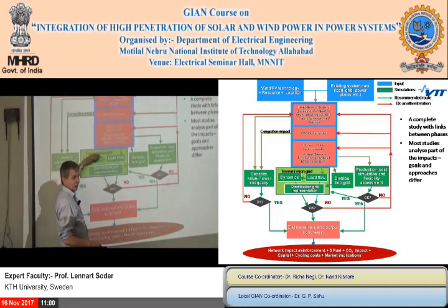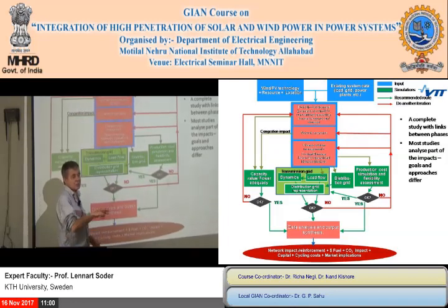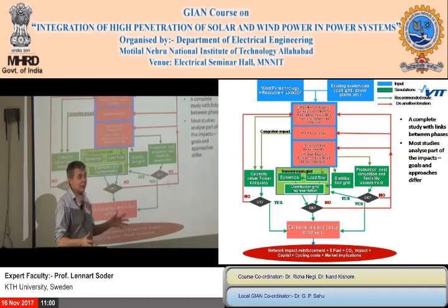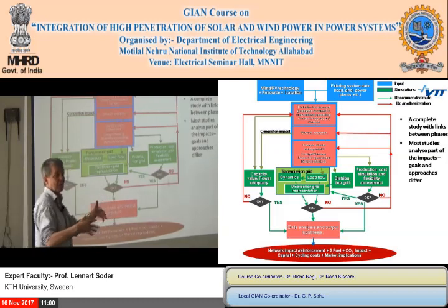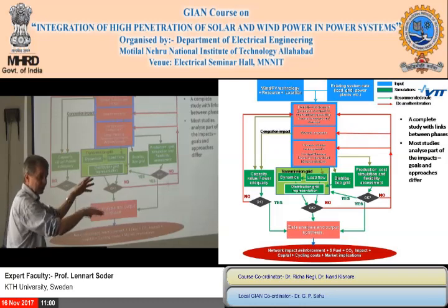While for most of the things here, I mean, load flow, there are probabilistic load flows, but dynamics is always done for a very specific situation. If the wind is like this, if these coal plants are there, if we have a transmission like this, if the load is like this, and we get a disturbance, then of course we get these kind of things. In reality, you have a huge amount of possible situations. I mean, just take India. How many combinations do you have of outages in different power plants, and the load is changing like this, there, and so on.